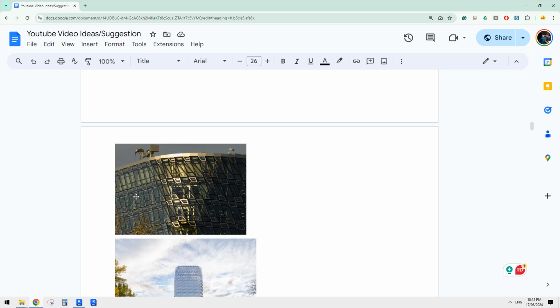One is if these walls are vertical, we can quite easily use curtain wall to create this. If this wall is not vertical, it's a slanted wall, or even something like this, we have to use either pattern-based family or adaptive family to create this.